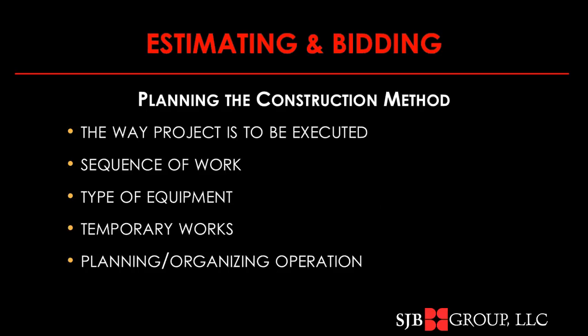And you're also going to probably want to do some comparative studies. In those, you're going to evaluate several different approaches. You're going to compare the cost of production for the different types of equipment to do each possibility. If the quantity varies depending on how you're going to do an alternate, you need to base it on the appropriate volume of quantity. You need to consider the cost of alternative materials. And then finally, you're going to compare the estimates of each of these methods to determine the one that is most cost effective and meets the other requirements of your plan.